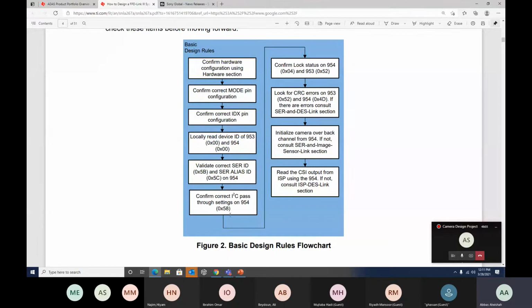It doesn't have to be in this structure, but it needs to have a flow to it. If I did the stack up, great. If I didn't, I go back and I ensure that I got my stack up corrected. Because it could be a stack up issue, where with vibration you have an intermittent connection and the image is not given to the serializer.